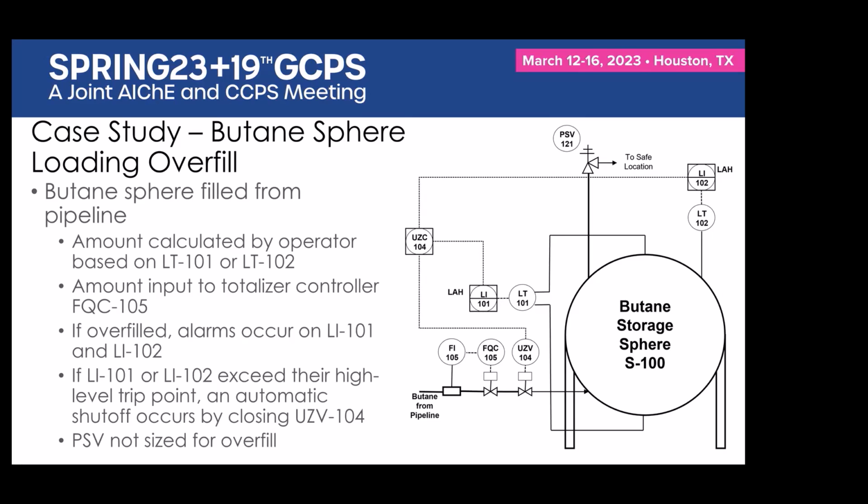So clause 8.3.2 says the average frequency of dangerous failures of a BPCS as an initiating source shall not be assumed to be less than 10 to the minus 5 per hour.